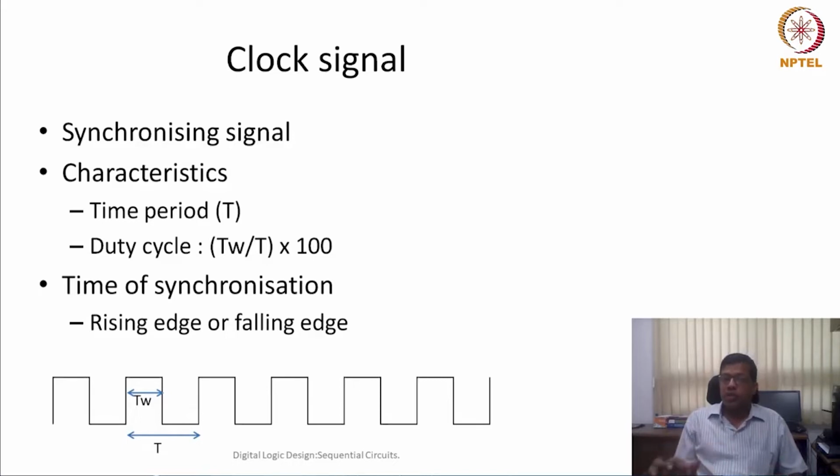What do we mean by synchronizes? Particularly in synchronous sequential circuits, whenever all the inputs change at the same time, all the outputs will also be reflected at the same time, so they would be received at the same time. That means all the components, the various combinational logic, adder, multiplier, multiplexers, would be synchronized with one signal, that's called the clock signal.